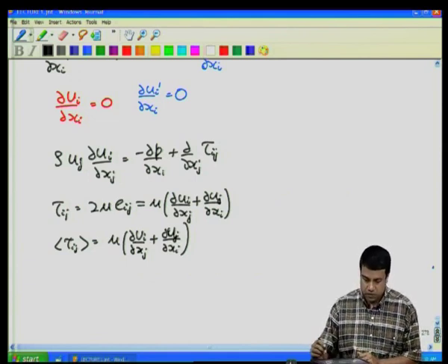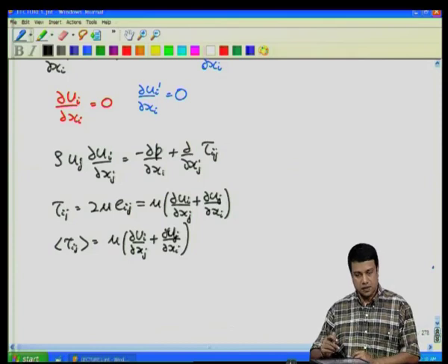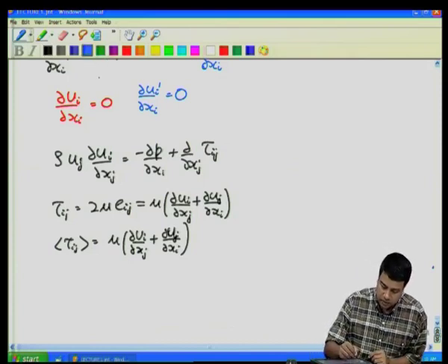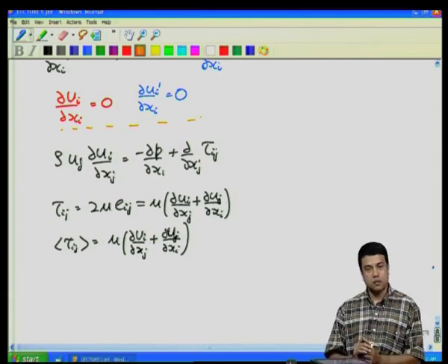So, if I write as I have shown here, I can separate out the mass conservation equation into two parts. One is for the mean velocity alone and the other is for the velocity fluctuations. If I can do the same thing for the momentum conservation equation, then I could hope to solve these two equations in order to find out what the mean velocity profile is. So, let us write down the momentum conservation equation in terms of the mean plus the fluctuating velocity.